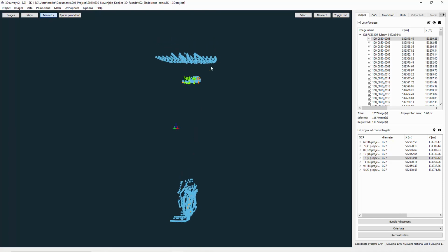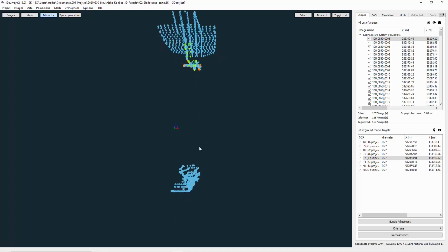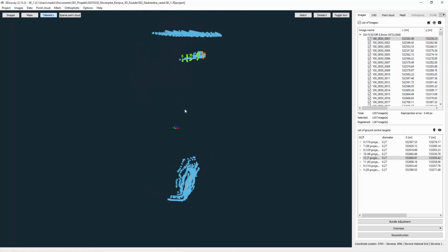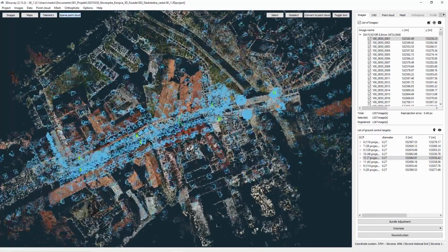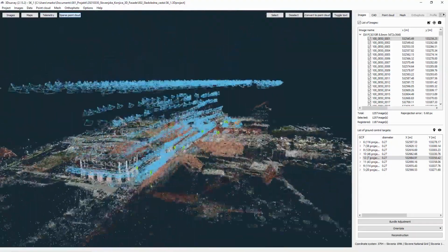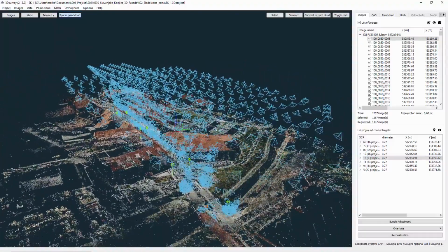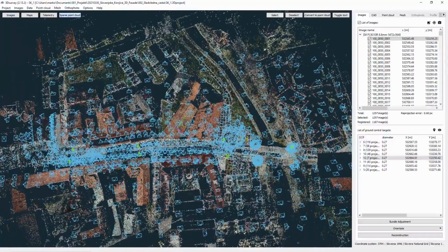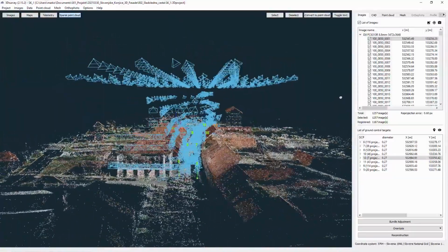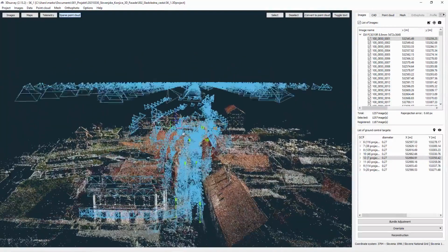The thing was, here we have an RTK signal and accurate position, then we turn off the drone and start with manual flight. We didn't get an RTK position and the height was not calculated referentially correctly, but nevertheless we get the end result like you can see it here after the bundle adjustment. So all cameras are correctly positioned after the bundle adjustment. You can see we also use 1, 2, 3, 4, 5, I think 8 ground control point targets, and those blue pyramids nicely show us the position of cameras.